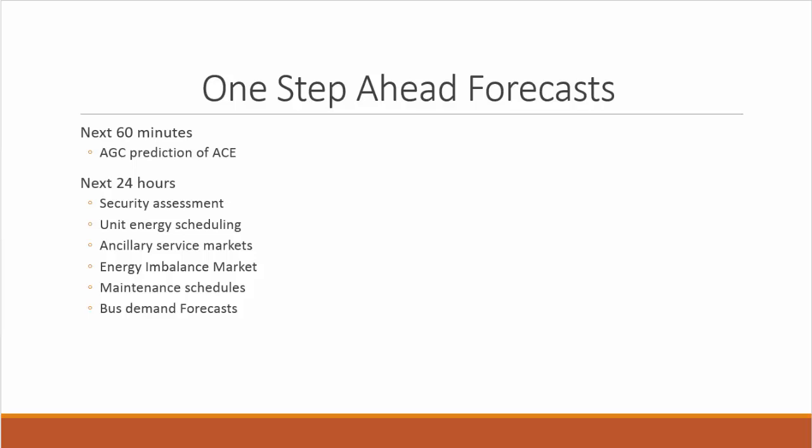One of the things we'll talk about briefly at the end is bus demand forecast. If we're going to do a power flow for 2 days from now at 3 o'clock in the afternoon, we have to have a good idea as to what the demand is going to be at every bus in the power flow. It doesn't matter how feeders are switched from one bus to another, as happens in operations, or what the transformer taps are; we have to be able to include those factors into our forecast so that we can do the proper maintenance and outage scheduling in the future.